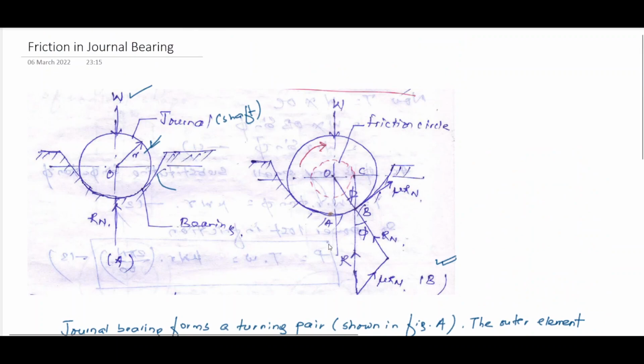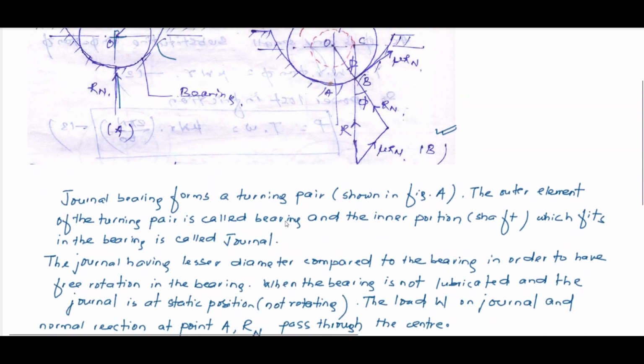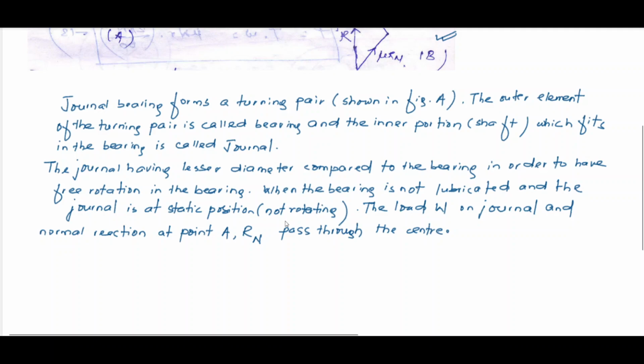So here it is at the static position, so the load acting on the shaft and the normal reaction offered by the bearing pass through the center, because it is at the static position. The bearing is not lubricated at this instant.